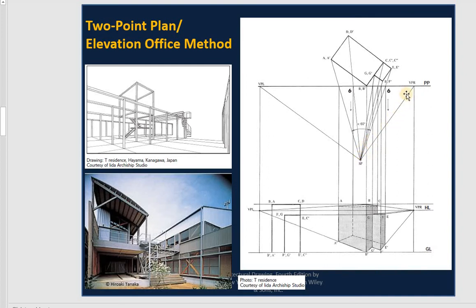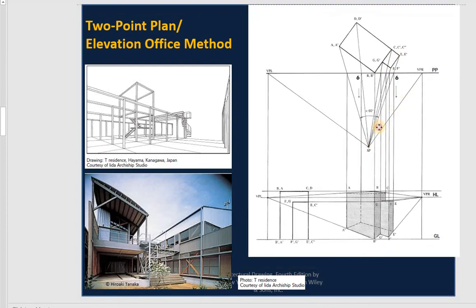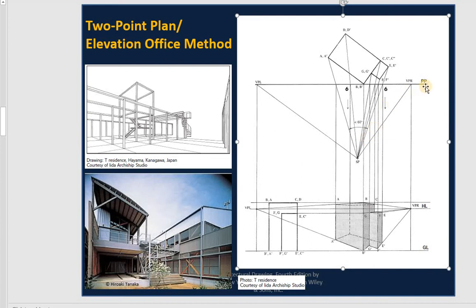After that, you draw two lines on the left and the right side. From the standing point, you draw the line parallel with one side here. This is the line you need to draw parallel with that one. And when that line cuts the picture plane, you drop down vertically to the ground line. And this point, where it cuts the horizontal line, the horizontal line is where your eye can look at the projects. When they cut this one, that's what you call the vanishing point. And you combine with the point right here.